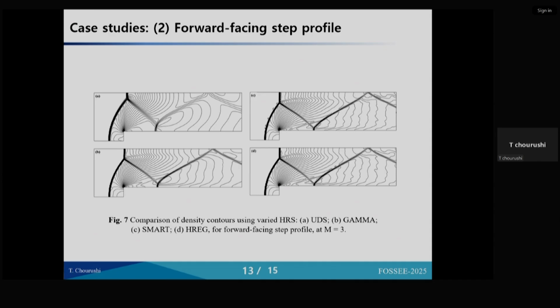In order to converge it, we need to tune special limiters and put more restriction on the relaxation factor. Then I can make it converge, but it consumes a lot of time. The results I compared here do not use any extra relaxation factors to make the scheme converge; they use the same set of relaxation factors and conditions.